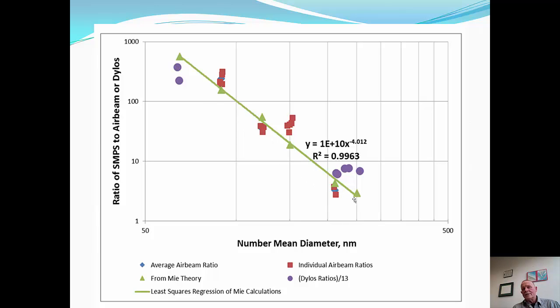As the particle size continues above here, these numbers get closer and closer to 1. So what you're really reading with a very sophisticated number counting device, with the inexpensive optical particle counters, or any optical particle counter for that matter, is very good out in this region. Back here, it's not so good.